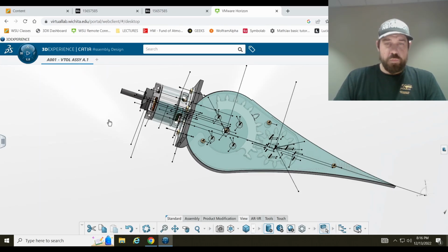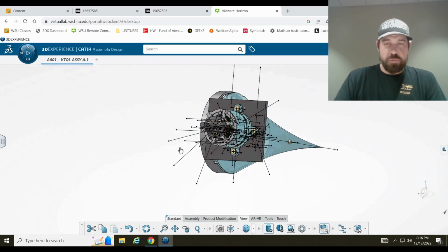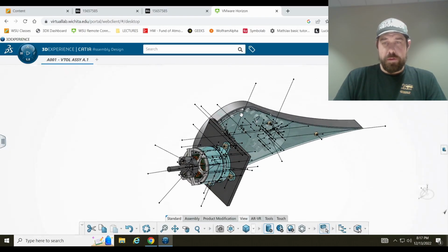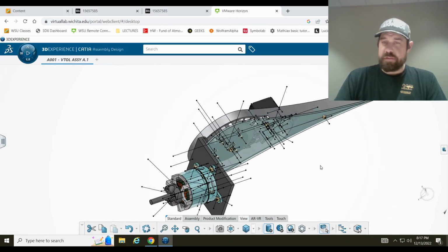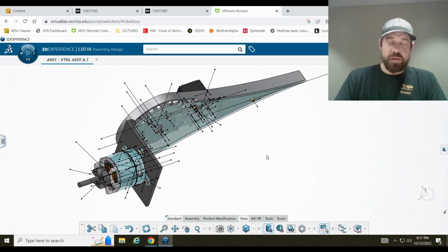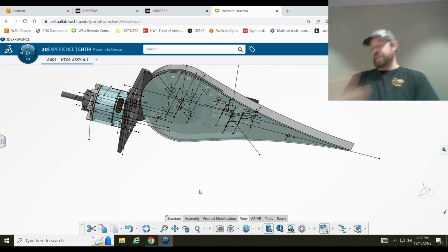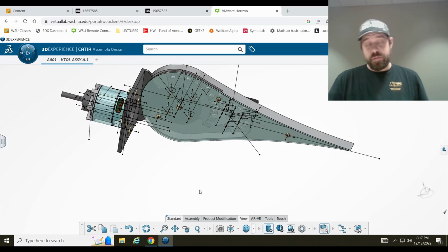Each part has one running along any rotational axis that it has so that I could line up axes easier in the engineering connections. And then they also have another one along one of their orthogonal faces so that I could use that as an angular reference between that and another part's face to prevent rotation. So that's how I made the rigid connections.